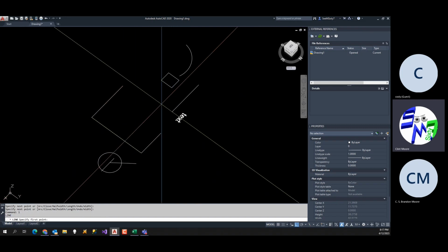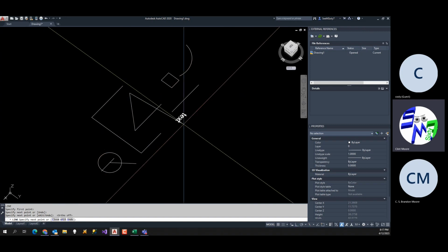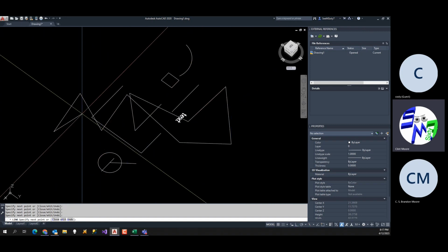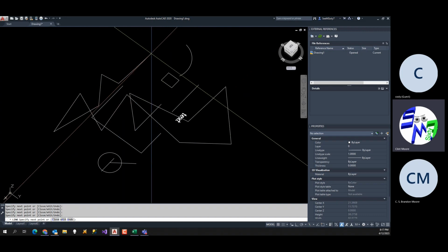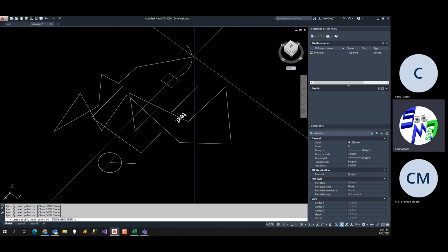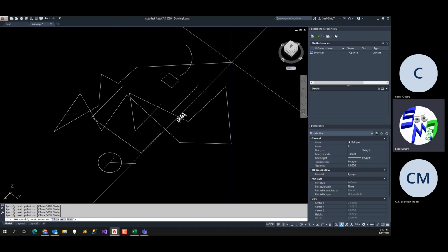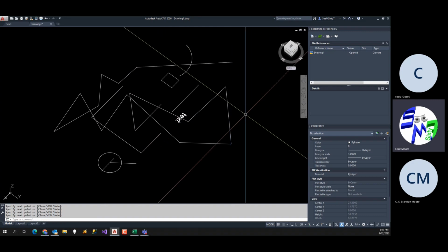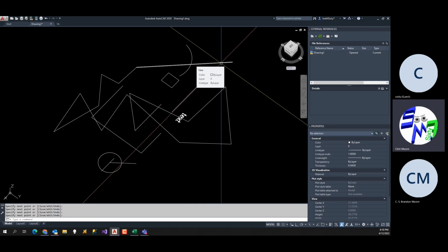If you start drawing a line though, the problem is, when you turn off ortho, you could be drawing on multiple Z elevations or not. Typically you're going to stay at the elevation you're at, but if you start snapping to different objects that have different Z elevations, you're going to be picking on those things. Something that's nice about a P line is a two-dimensional polyline stays flat. It will not go in 3 dimensions. There is a 3D poly command that you can utilize if you want that. But there are 2 different things. Lines are not limited in the Z elevation. They can go up and down however you want them to.